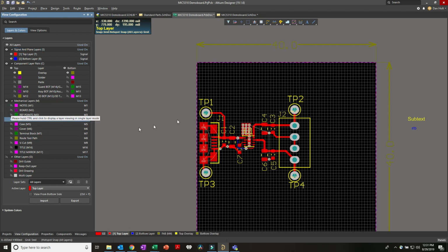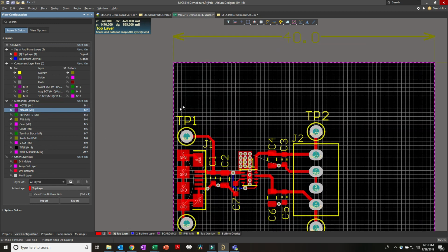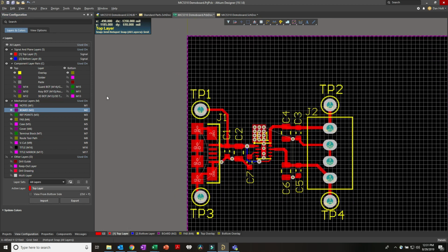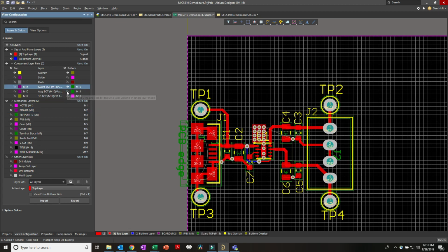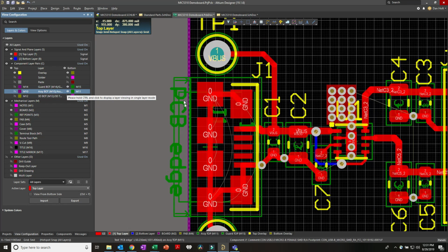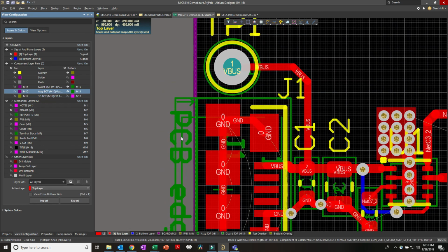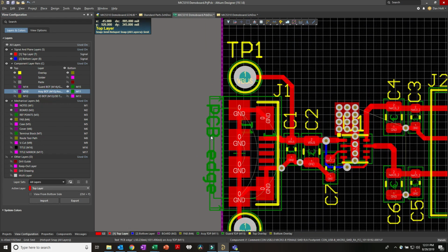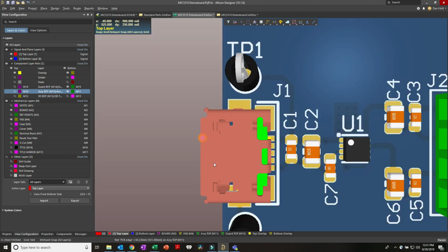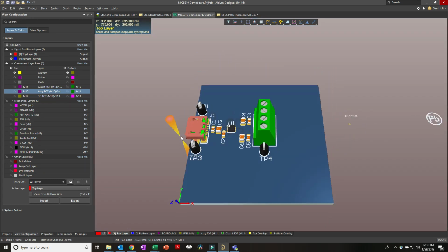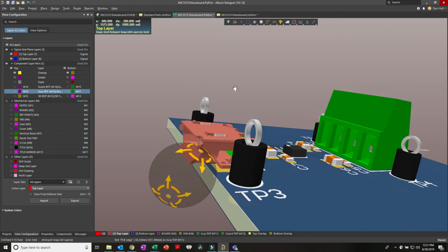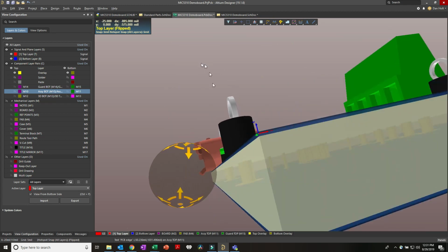Over here, again, tab 20 mils. Enter. Okay, I'm seeing one rat's nest right there. Until I do a ground plane, there's no connection between these points. No big deal. Okay, before I do any ground plane, let me go ahead and clean up the borders of this design.